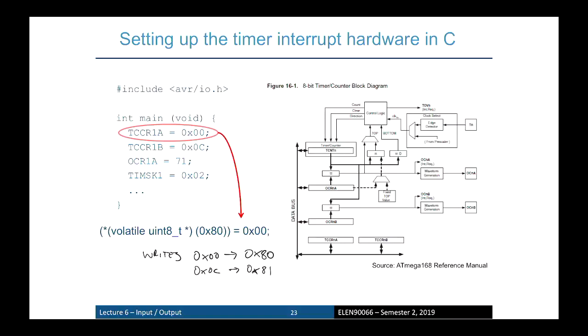Now, the idea behind all of this is that this is architecture dependent. You're actually writing a value into a timer, right? The value C. The top end of the timer is 0 and the bottom end of the timer is C. And the timer takes up 2 register locations. But the point is that using nice bits of code here where someone has already gone and defined these for you means that you don't need to be worrying about what these real locations are.